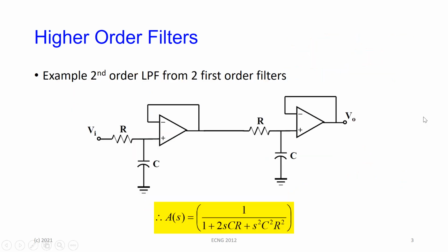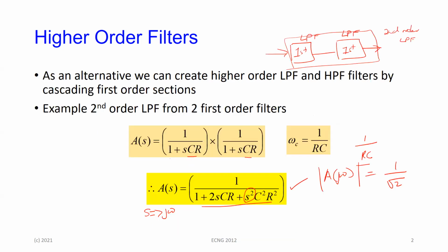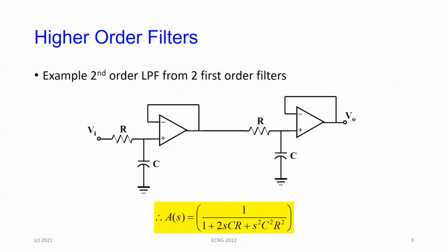This is what the circuit, of course, will look like. So the difference here now is that we have 2 op-amps instead of 1. So you're now dealing with a trade-off. In one case, the filters that we discussed last week, Tuesday, had one op-amp and 2 capacitors and 2 resistors. Here we have 2 op-amps and 2 capacitors and 2 resistors. But the structure and the design is substantially easier. And of course, it's a lot easier to derive this type of transfer function than it is to derive the Sallen-Key type.